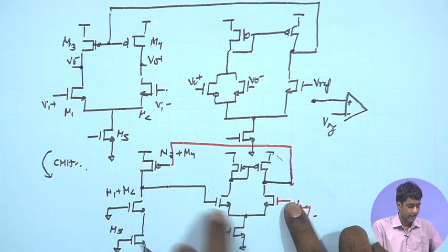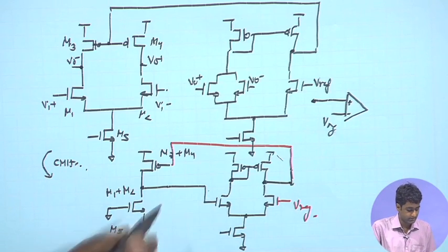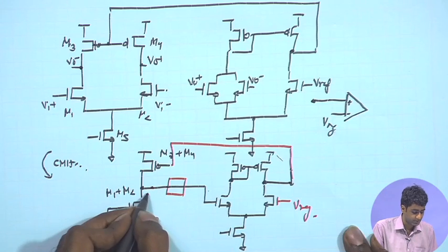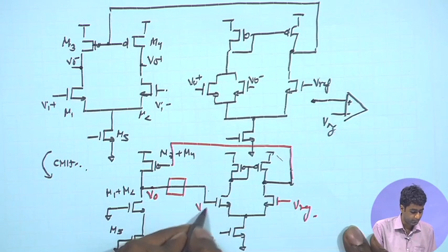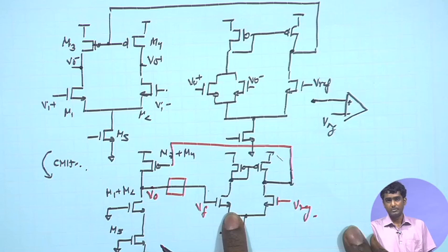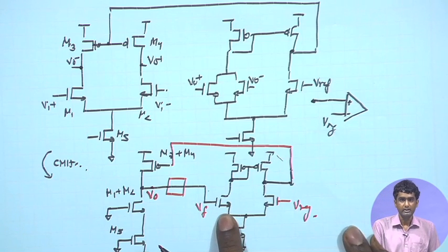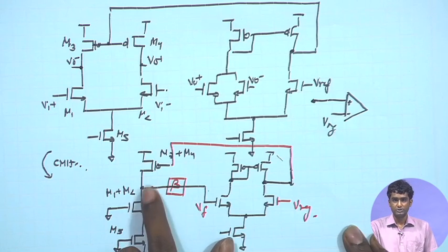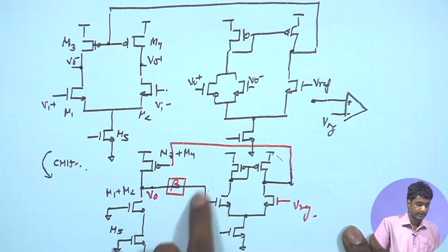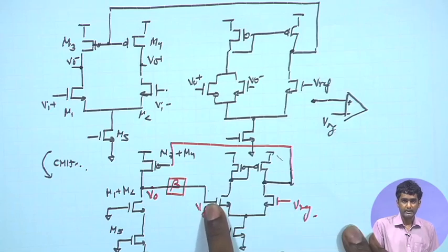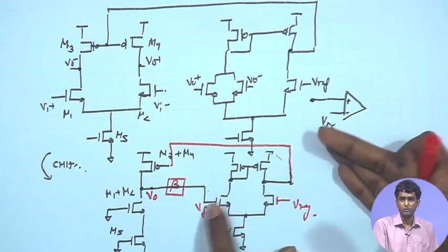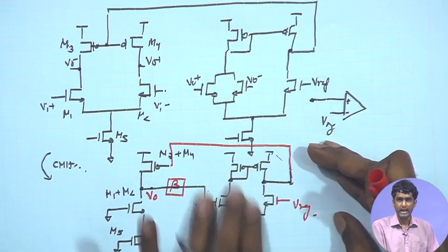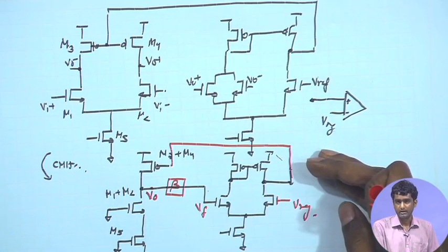are applying the input, and the feedback signal, as we have seen yesterday, can be seen as voltage sampling. So, whatever final voltage is coming over here, that is directly applied as the feedback voltage on the other terminal of the differential amplifier, which is effectively the negative terminal. So, here is our sampling network, which is sampling the output voltage produced by the second stage, and it is applying that sampled output voltage to the effectively inverting terminal of this overall two stage amplifier, formed with the help of the main differential amplifier and the common mode feedback amplifier.